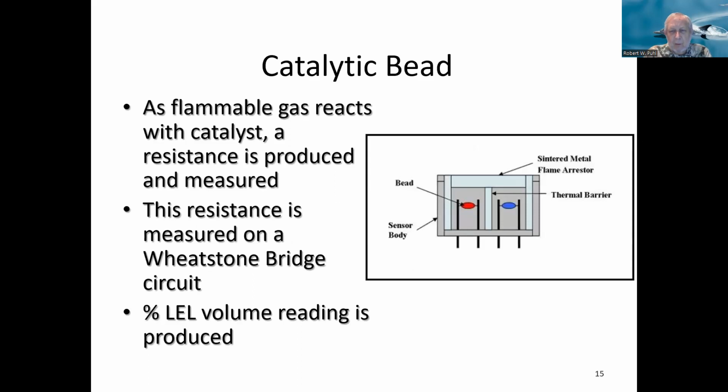As flammable gas reacts with a catalyst, a resistance is produced and measured. This resistance is measured on a Wheatstone bridge circuit, and the percent of LEL volume reading is produced.